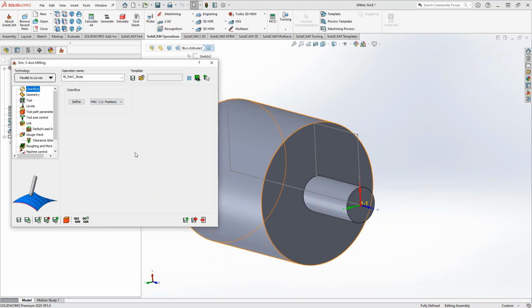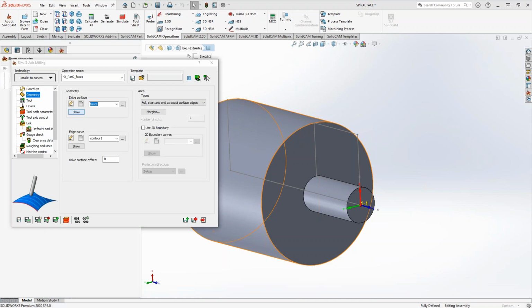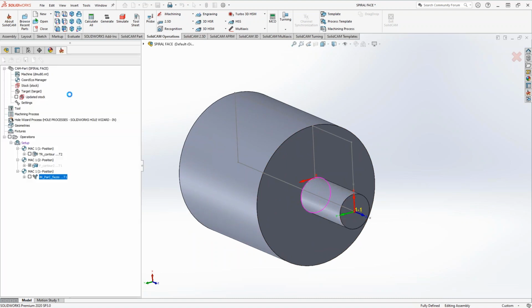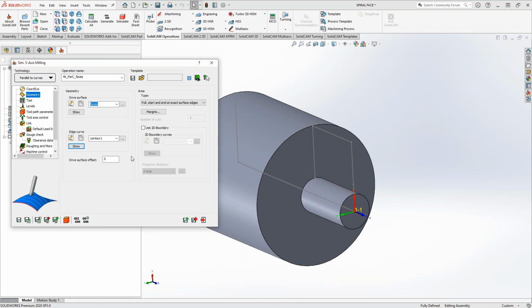Like we saw yesterday, there's a little extra steps to do these kind of higher level toolpaths. But in this case, we're actually going to be better off because we're going to get a nicer looking toolpath. So what I'm doing here to kind of recreate that, but in 4th axis, is using parallel to curves. So that's going to ask for a surface. So that's the surface right there we're trying to finish. And it's going to ask for a curve to stay parallel to. Now, we're looking at this pretty much in the same way. I've chosen that same contour there. I want to do the same sort of toolpath, getting a little bit more 4th axis ability in there. But I'm still basically just choosing a curve to stay parallel to, just like I kind of did in profile. So that's all the same there.